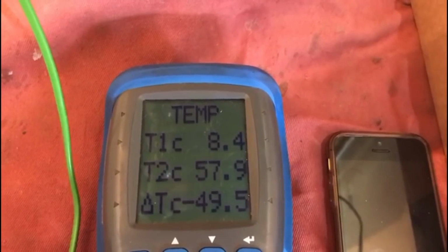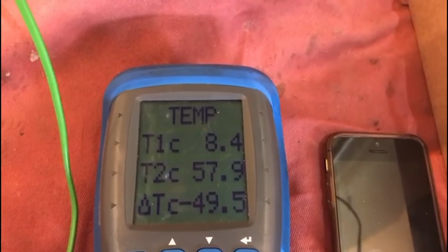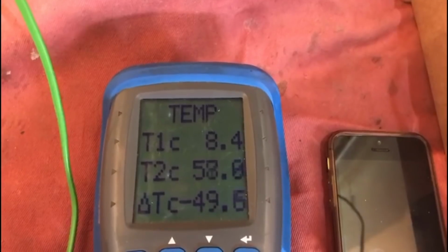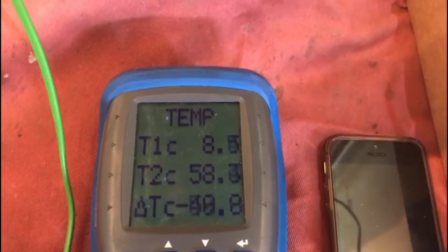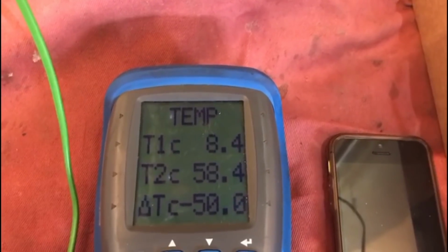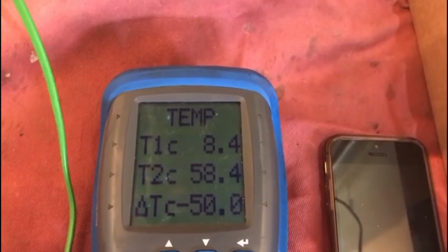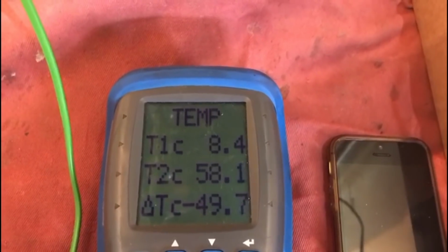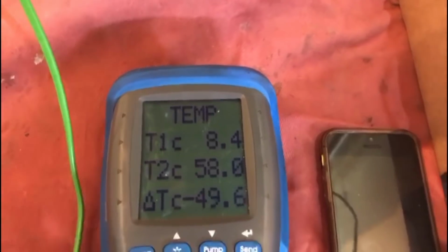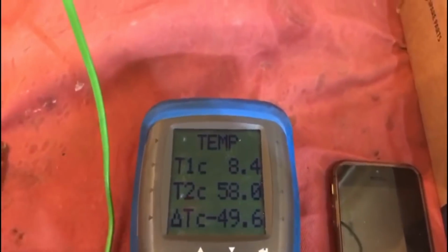It would overheat, the temperature would drop back to around 20, 25, and then try again and try to get back to 35. The fact that I am pulling a lot more heat through my plate heat exchanger and it is staying at a steady temperature just shows me that my plate is working okay.